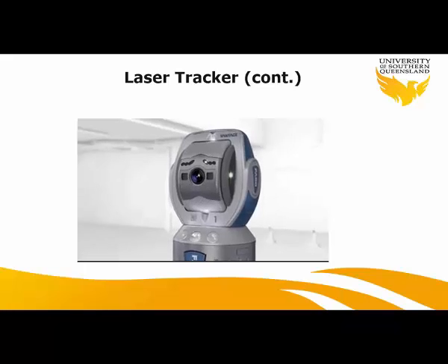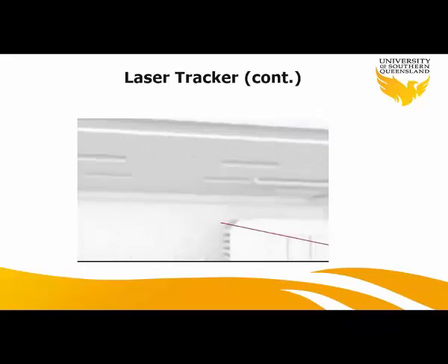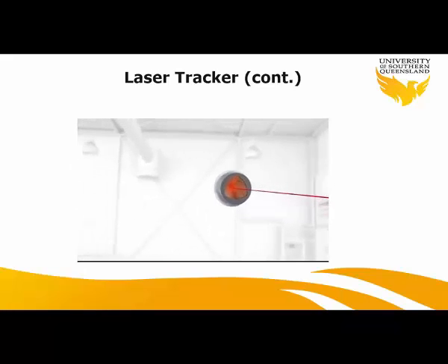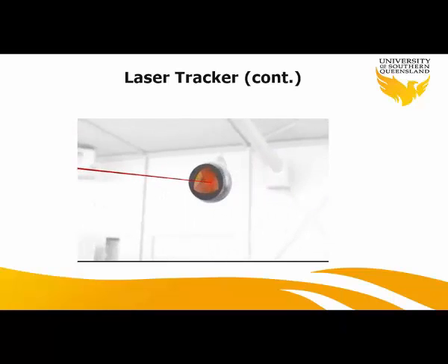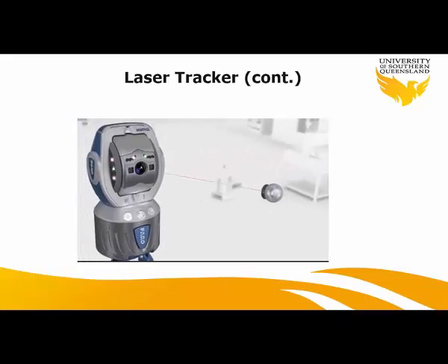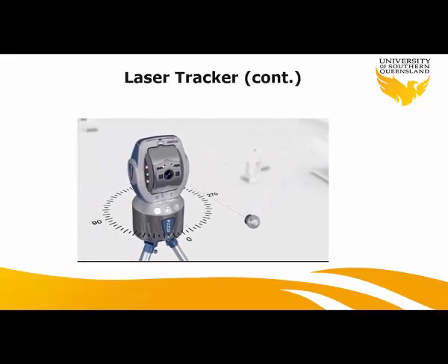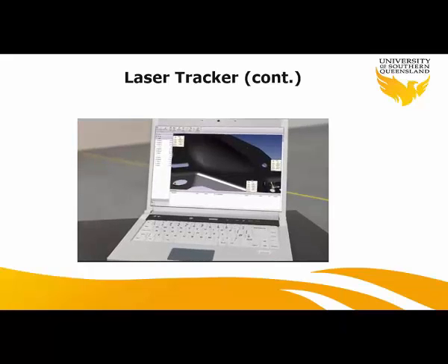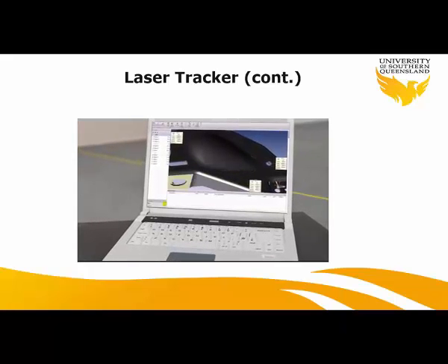The laser tracker measures 3D coordinates by tracking a spherically mounted retroreflector, an SMR, that is in contact with the object. Two angle encoders measure the elevation and rotational angles, while a highly accurate absolute distance measurement is used to determine the 3D position of the SMR. The software stores these values and allows for the comparison with CAD data.